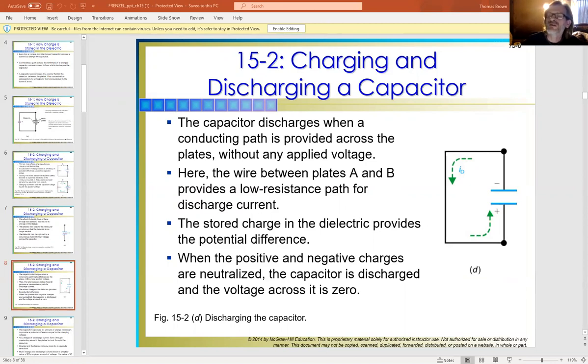So now comes the interesting thing of discharging. If we wanted to discharge it, we would have to provide it a means. Now notice in the diagram here, there is no voltage source. In this case, the capacitor could be considered the voltage source for this particular circuit. If it's fully charged, let's say it reached the 10 volt potential, it would sit there, and if we gave it a means to discharge, it would give us that 10 volts. And it's not forever. How long it takes is based on the rating of that capacitor.